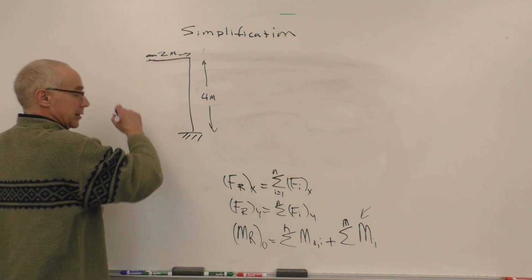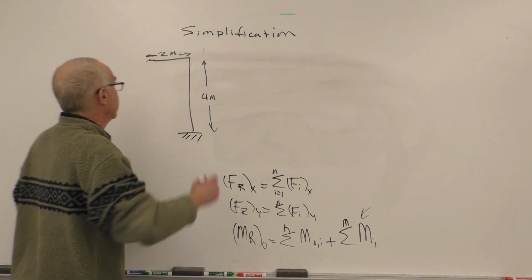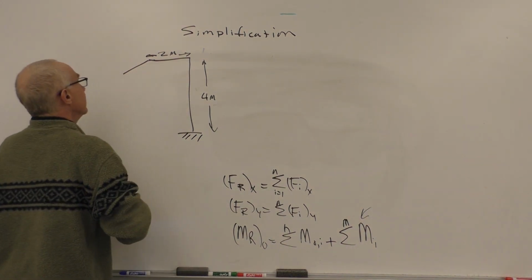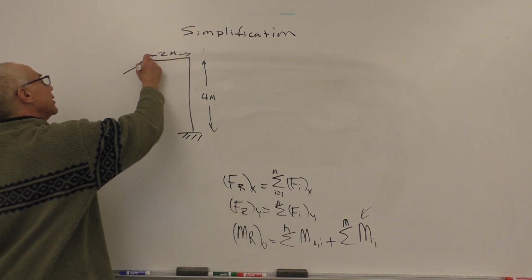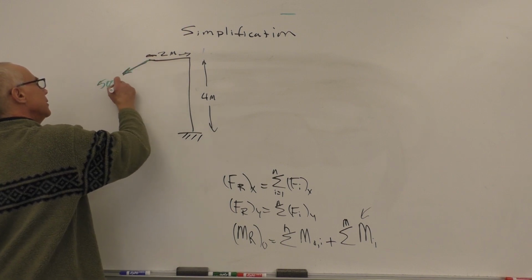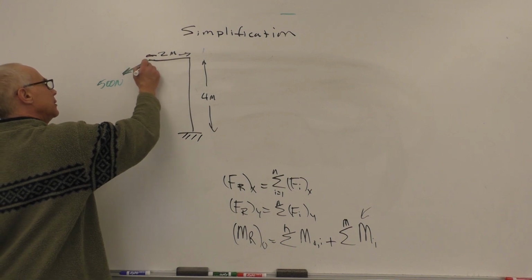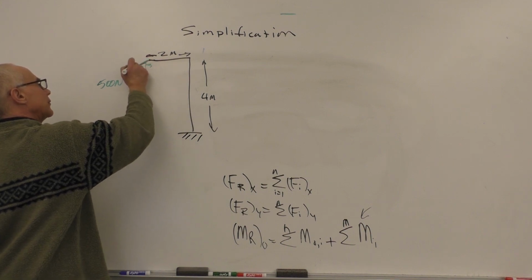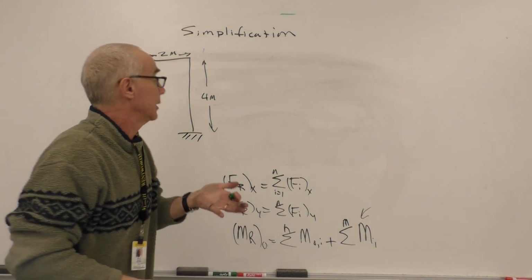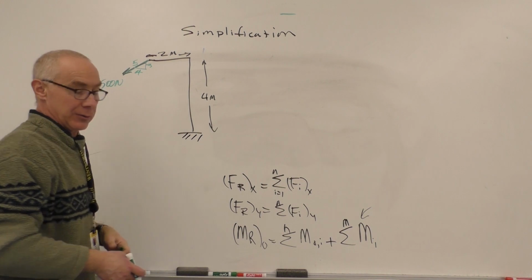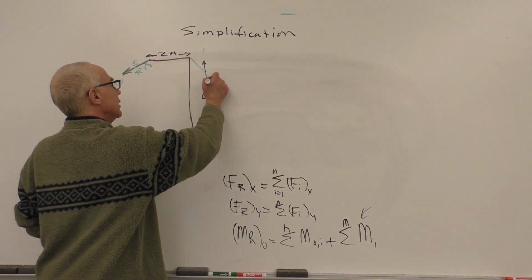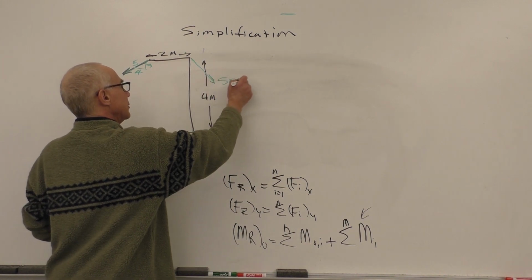The first force, they're both 500 Newton magnitude, only this one I'll do in another color. Let me do it in green. That worked. Green, 500 Newtons. And we'll make this a 3, 4, 5 triangle, and that helps us get the slopes. It's actually much easier than if you have the angles specified, because we know the ratios right away. And on the other side, this one's also 500 Newtons.